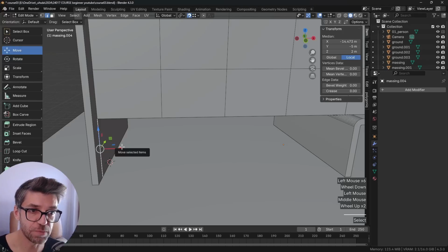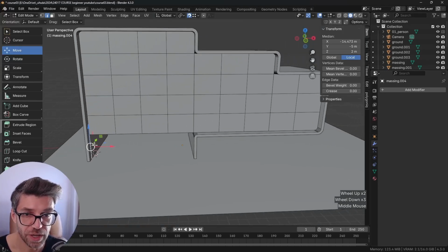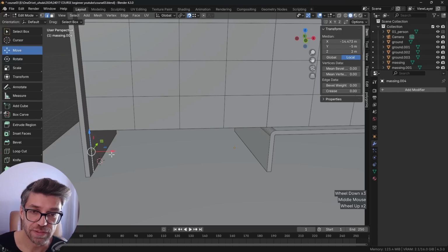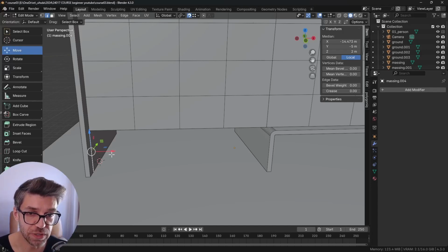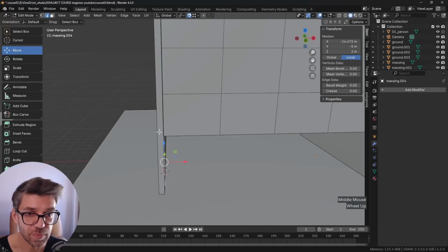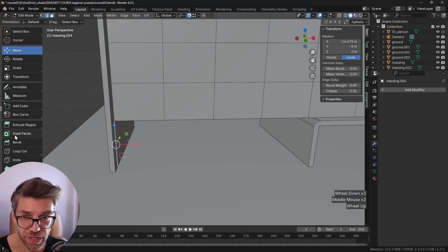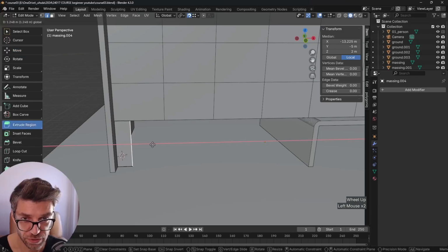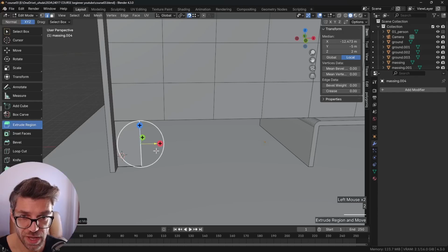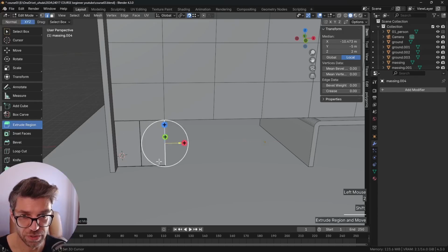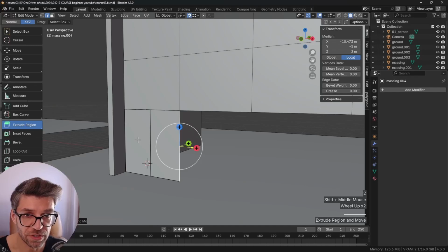Great. And we can also make this parametric as well, in the sense that maybe we have not a completely glass facade, but we have a solid element, so kind of like a base, and then glazing in between them. So we know our modules are 4 meters, so we can work with that same dimension. So let's extrude this 2 meters. And now let's extrude it again 2 meters. So one part is going to be solid and the other one is going to be glass. And then we're going to array that.